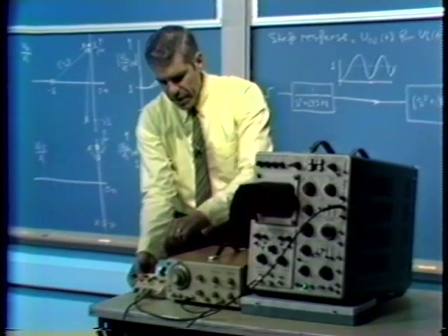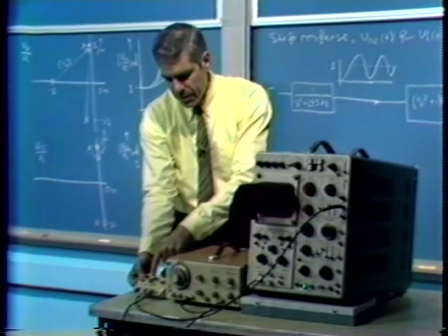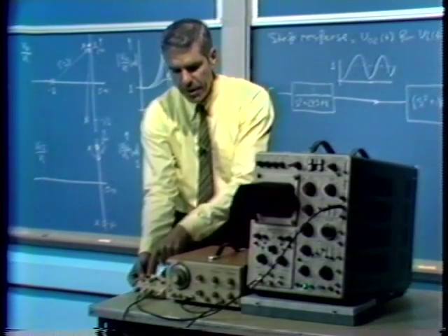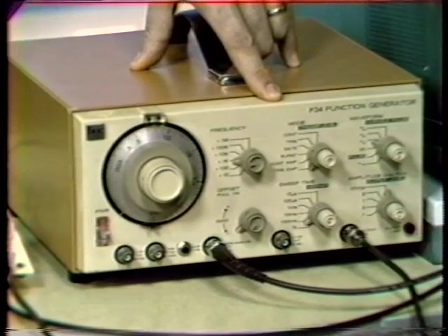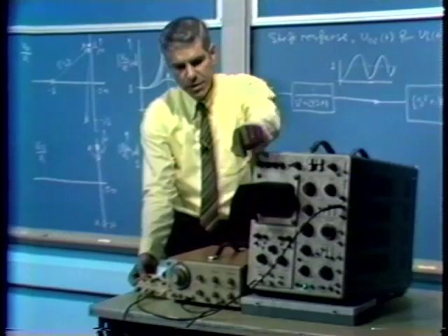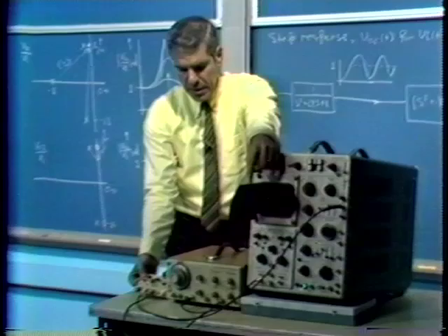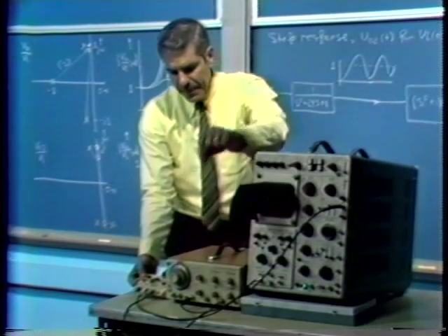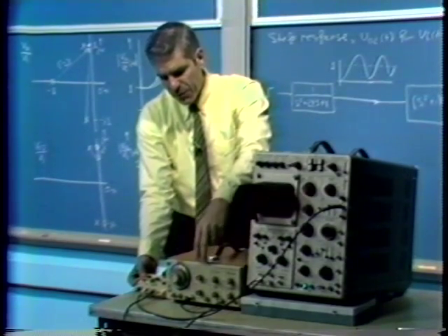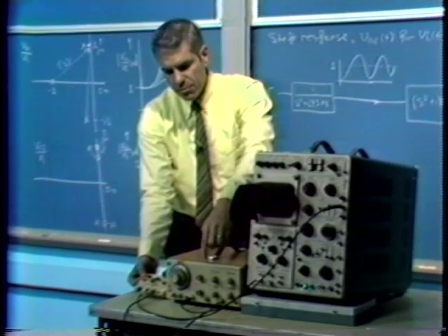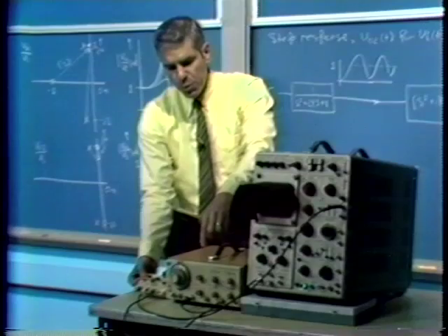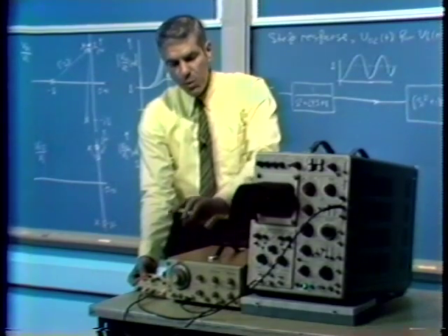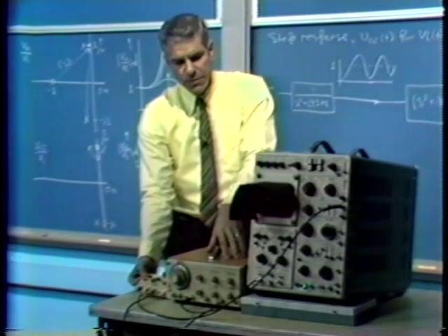And what we then do is drive this frequency selective amplifier with a swept sinusoidal signal, which allows us to plot its frequency response. We look at the resultant frequency response on the oscilloscope. For reasons of getting a clear presentation, it's easiest to do this with a sweep and without putting in the peak rectifier and all of that.